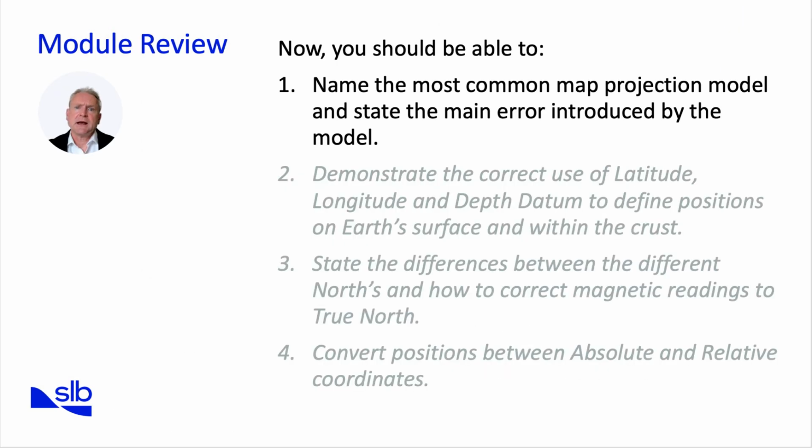Okay, so as a recap of this section, we have gone through some common map projections and saw how each introduces controlled distortion. You should now be able to identify which projection is in use and what errors it introduces. In the next section, we will introduce the most common projection used in the oil industry, which is the Universal Transverse Mercator UTM system. Second, you'll learn to use latitude, longitude, and depth datums properly. These are the foundations of defining position, whether at the surface or within the crust.